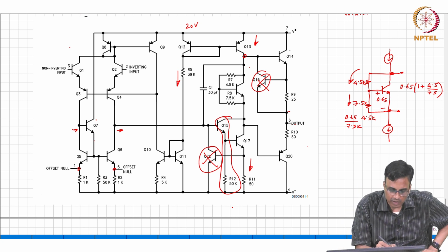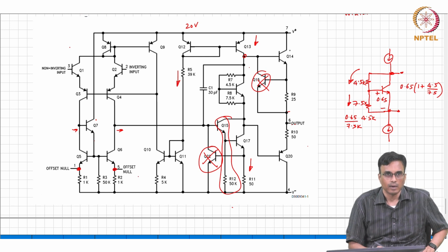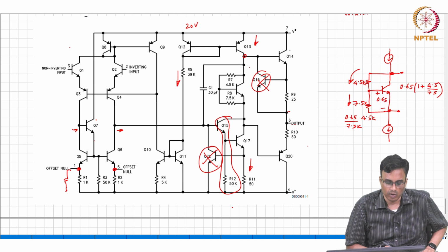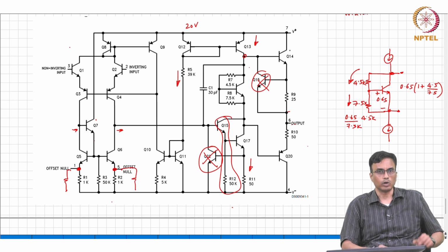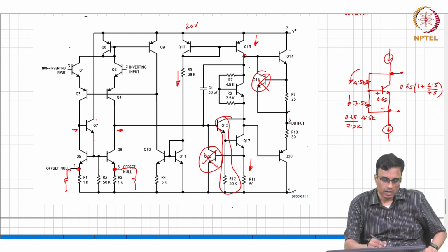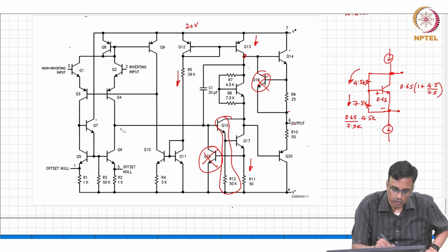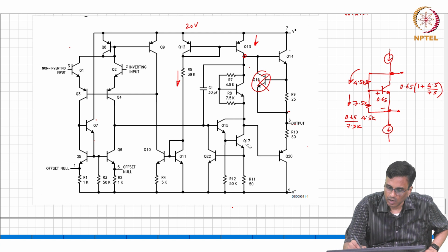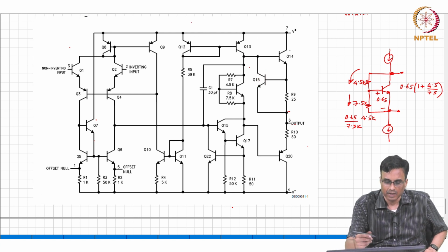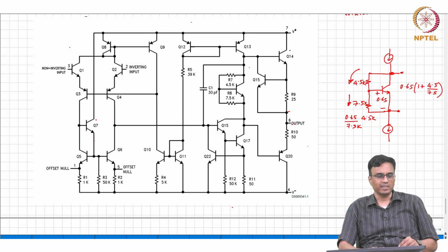So you have these two terminals coming out, and you can add a resistor to ground there, or on this side, to be able to turn a knob and nullify that offset. So that is a quick overview of the 741. As you can see, it incorporates a whole bunch of things that you have not learned.